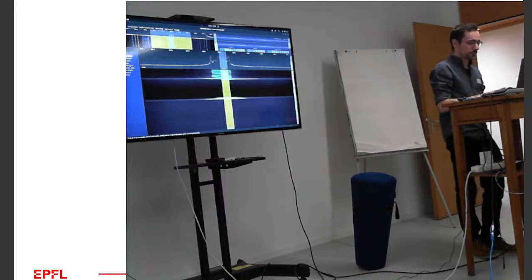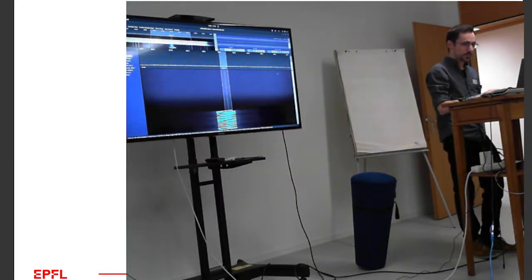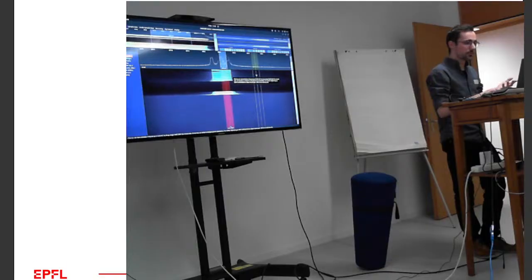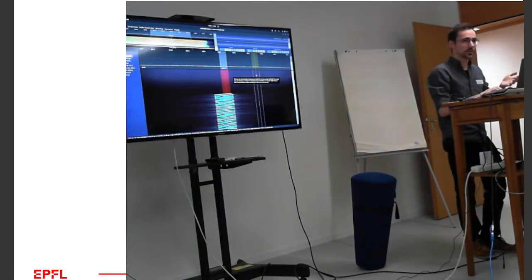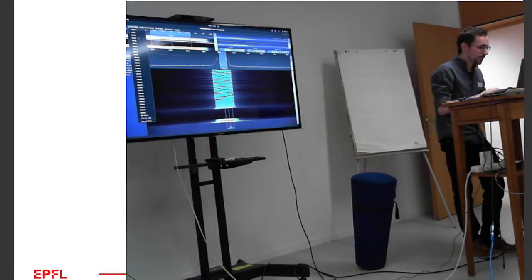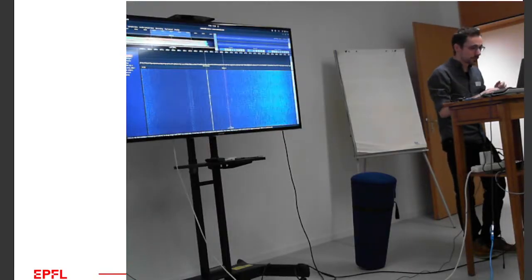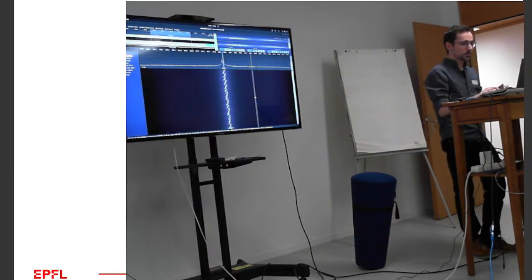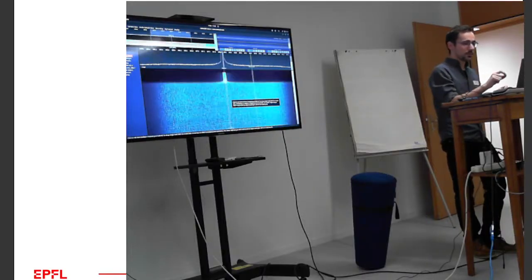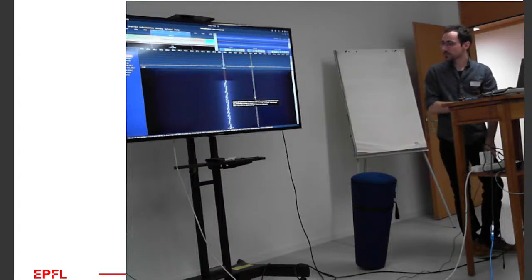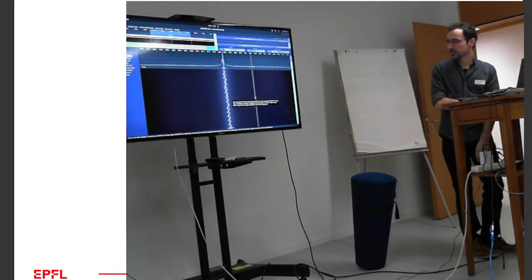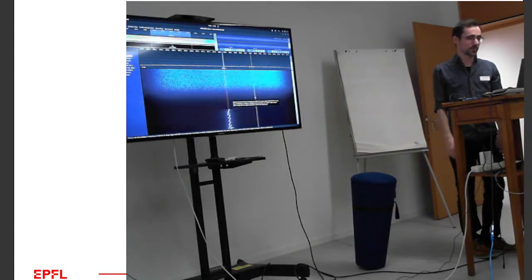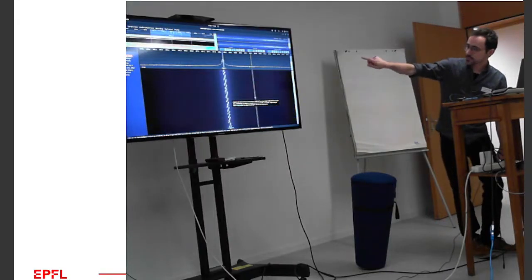So can you say how long it's transmitting, or can you figure out the spreading factor? For that, this tool is generic and it doesn't support it. But here, I send two signals. One is a short one with spreading factor 7, so we see a small pulse, and then spreading factor 12. But they send the same information. So there is really a difference in the real-time transmission. You transmit for more than a second, and there we can see the jumps.